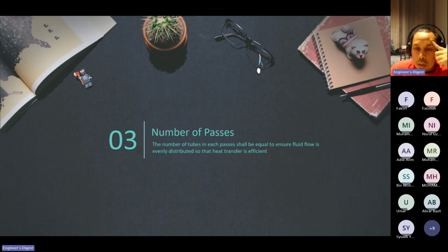Okay, is that answering the question? Okay, thank you. So basically, we have to check the limitation of the 10% margin, seek advice from PED, and also do the inspection by IRIS. IRIS and RFET use a device that goes inside the tube along the tube length, and from there they will know the wall loss of the tube. Later we'll have that class on RFET and IRIS.